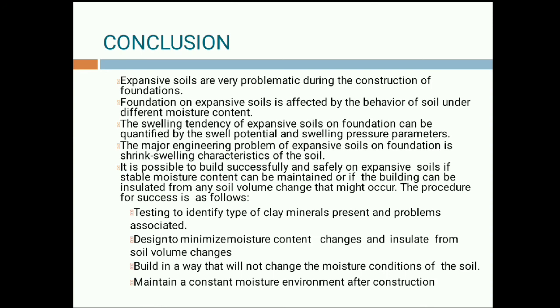Testing to identify the type of clay mineral present and the problems associated with it. That is, before constructing any kind of structure on expansive soil, we should find out the amount of clay minerals present in it, minerals like kaolinite, illite or montmorillonite. If there is a large amount of montmorillonite present in the soil, we should first do ground improvement techniques, and only then make any kind of structure on it.